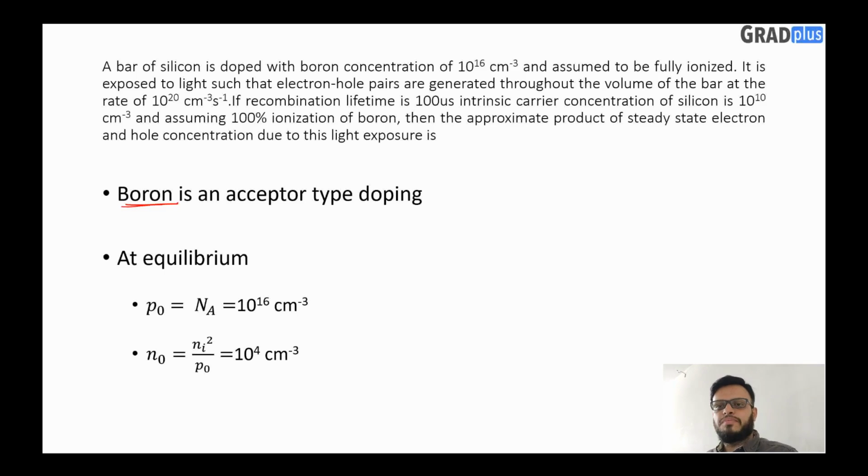So now the complete doping which we are going to do will be reflected as P naught. Here the same thing we have used. Now based on the mass action law, N into P is equal to Ni square.